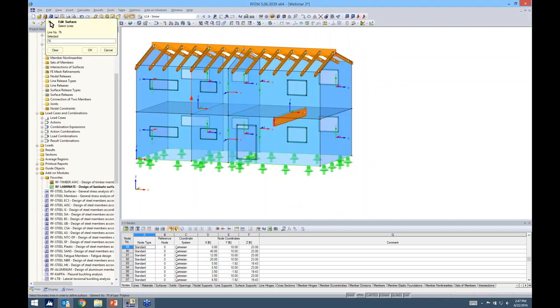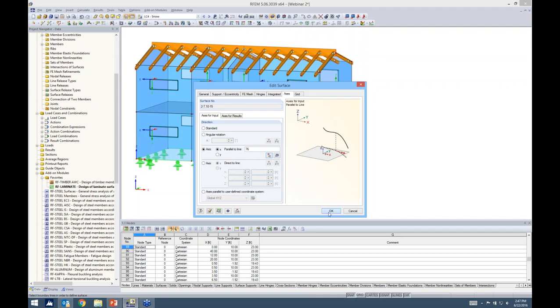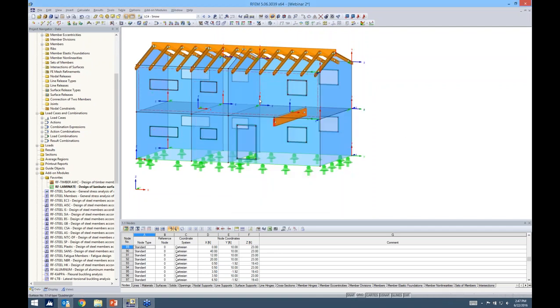And I'm just going to choose this vertical line here, and I click OK. And now you'll notice that all of my local axes are now oriented in the vertical direction. These ones come from the floor panels, so we don't need to worry about that. So again, very important detail. Otherwise, you risk your results being inaccurate because you haven't oriented the direction of the layers correctly.